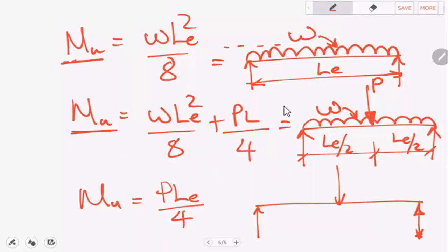Right, so if you have a beam like the ones which were given in N5, then you have to determine the position of the maximum bending moment from first principles, like what we used to do in N5. So you then have to apply that concept, determine the position where the maximum bending moment is acting, and it is that maximum bending moment which you use as the basis for then doing your beam design.